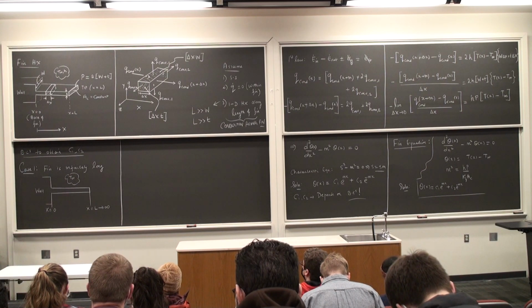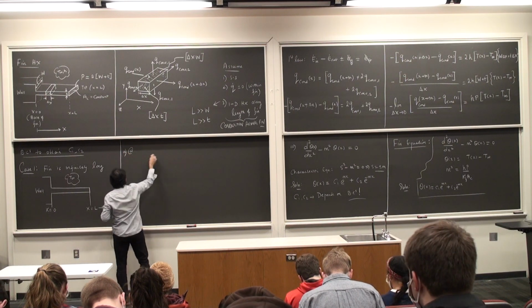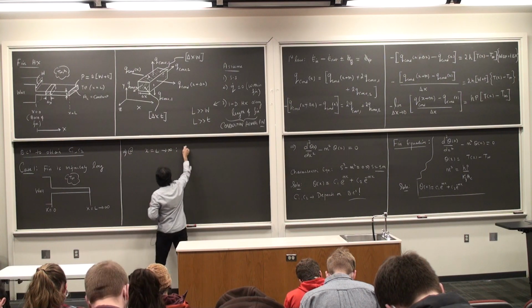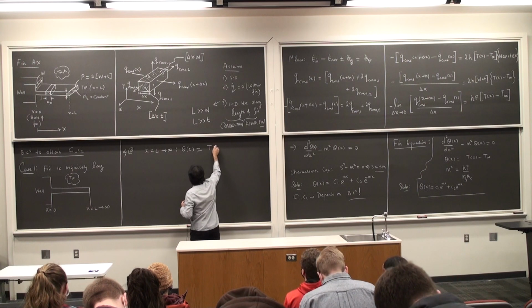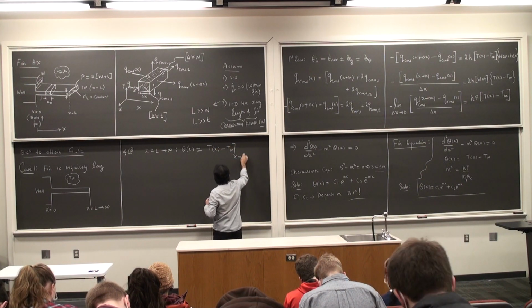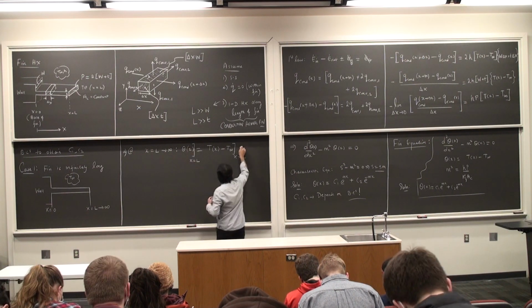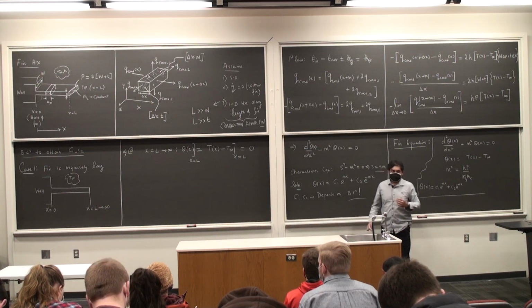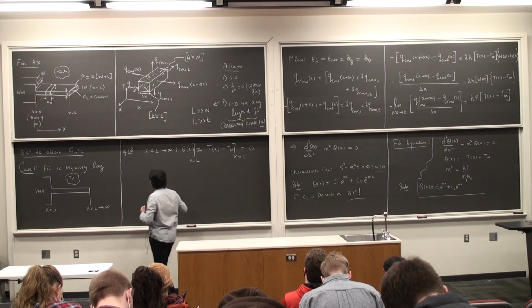Okay? So I have the first boundary condition at x is equal to L as L tends to infinity, theta of x, which is T of x minus T infinity at x is equal to L, is 0. Why is this? It's because as x tends to infinity, L tends to infinity, T of x at L is equal to T infinity.